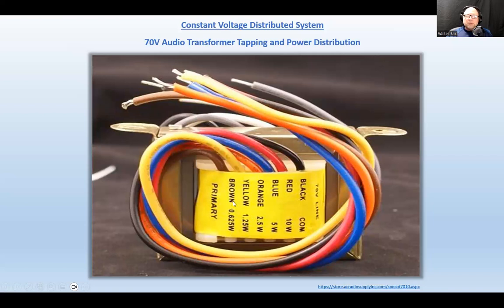So sometimes you're going to see transformers like this. What do you use? You use just a black lead to go to the common, maybe a black lead of the main audio line, and you choose one of those to be connected to the other conductor of the main audio line. The other ones, you just cut off and blind them, sometimes with marettes or wire nuts, sometimes with tape, just to make sure that nothing touches anything else by accident. Right?